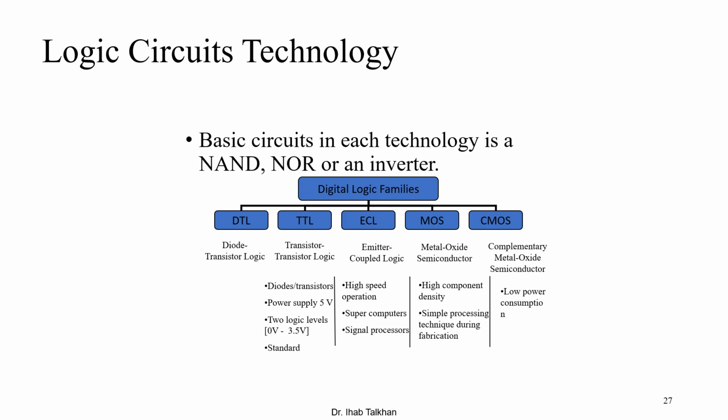That's why the CMOS uses two carriers. I didn't mention for you the TTL; the bipolar transistor is used for TTL. The bipolar actually uses two carriers in order to carry your data, and actually it's very fast because you have two carriers inside. But as MOS, it has only one carrier, that's why it is called unipolar. We have NMOS and PMOS.